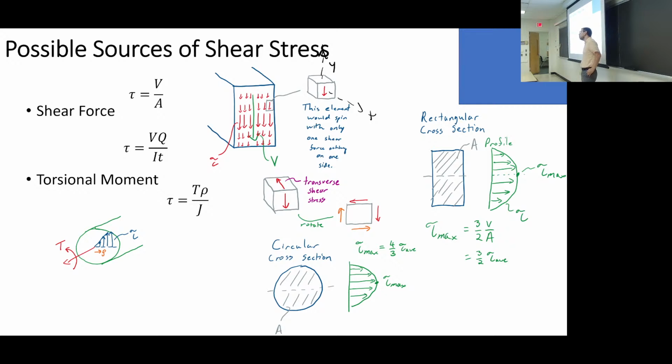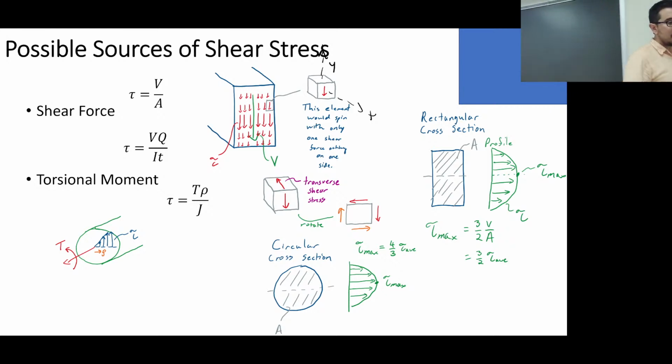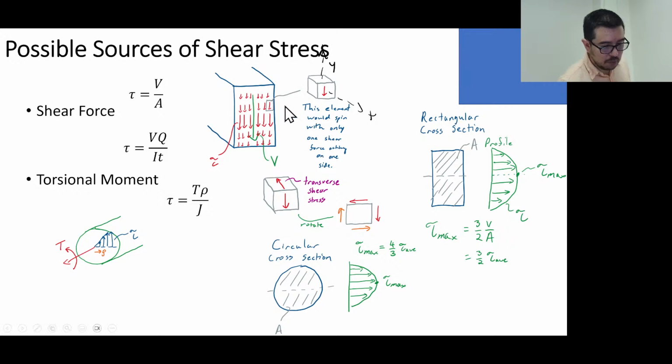They're the same magnitude, and because it's an isotropic homogeneous material, tau xy is going to be equal to tau yx. Do you see that this is technically the way of drawing things? This is technically tau xy. The way we've drawn it here, because it's on the x face, it's going in the minus y direction, so depending on how you define it, it's a negative tau xy, because at least it's going to be negative in that quantity.